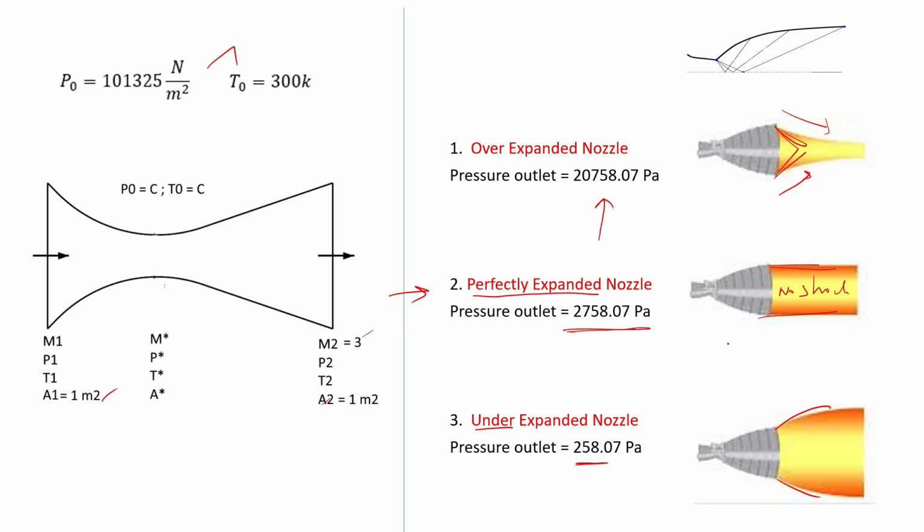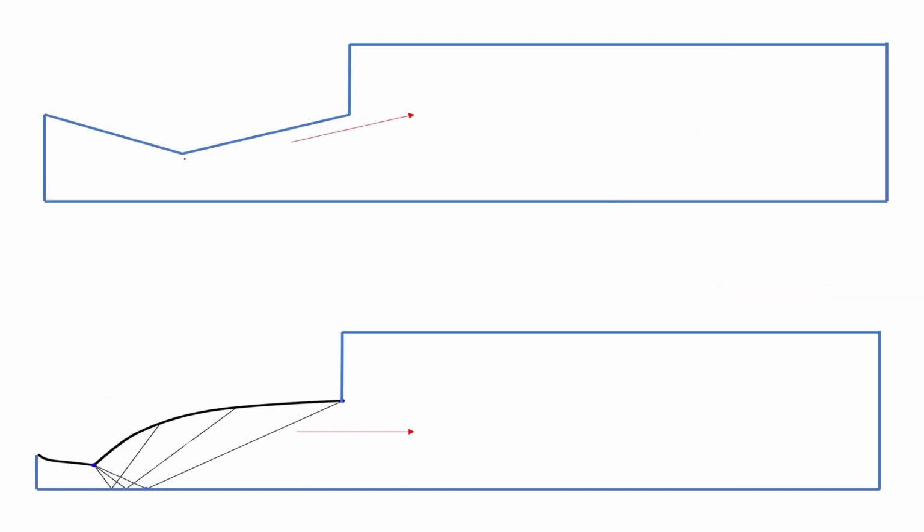And there is one more catch. We have taken just a simplified version of the CD nozzle, just 2 lines drawn. So at the exit the flow is not aligned with the free stream condition. Due to this divergence there may be a small expansion fan formed for the perfectly expanded case.